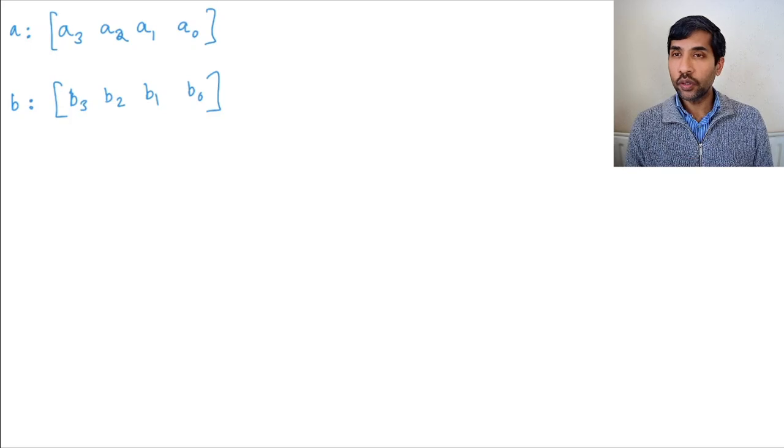Now, one way to do that would be to write an 8 input truth table and get the outputs, the sum and the carries for each of them. The sum will be a 4-bit sum and the carry will be a 1-bit thing. But as you can imagine, that's going to become very tedious, right? If you have 8 inputs, you'll have 2 to the power 8, that is 256 combinations, which would be quite difficult, quite tedious to do.